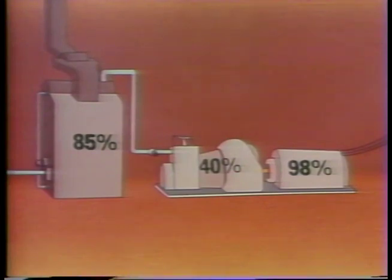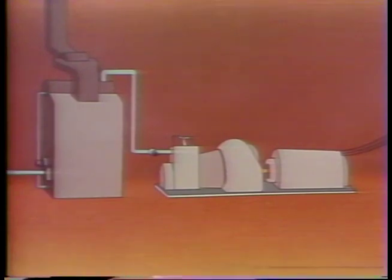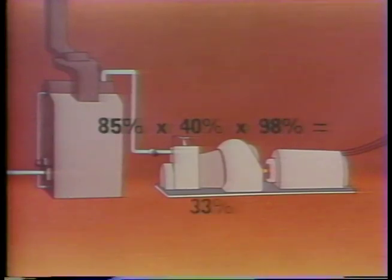Now, in order to find the overall efficiency, you multiply all the efficiencies together. When we multiply the efficiency rate of the boiler times the rate for the turbine times the rate for the generator, we get an efficiency of about 33 1/3%. That's about the same as the example we figured earlier. Nearly 2/3 of the potential energy in the fuel is lost. That's a lot of energy being lost. And if the plant is run inefficiently, even more energy is lost.